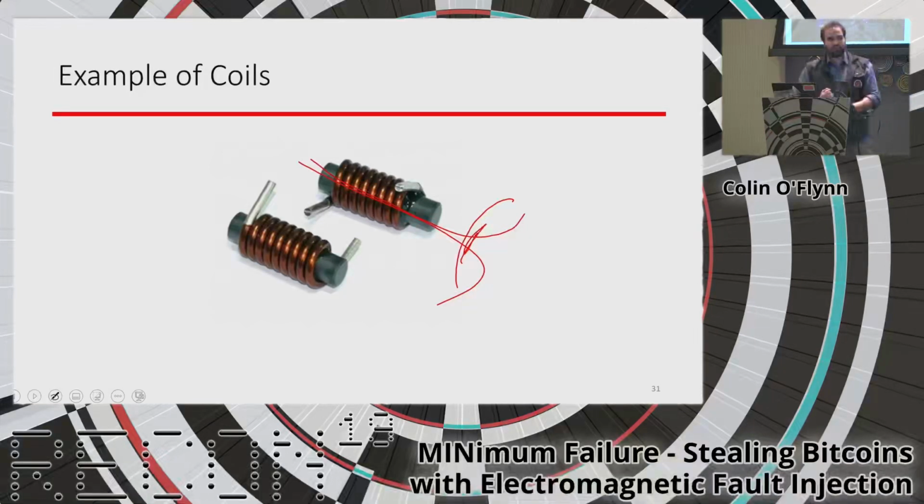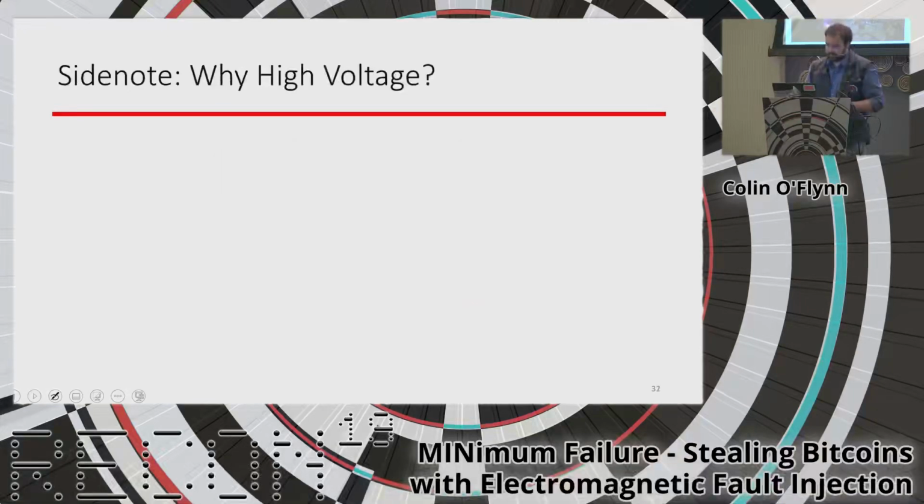This means we could do things like change instructions, mutating them from a load to a no-op. We could cause data not to be loaded in time so the results of the comparison are incorrect, or anything like that. In our case, we just want it to give us this result that skips the check.